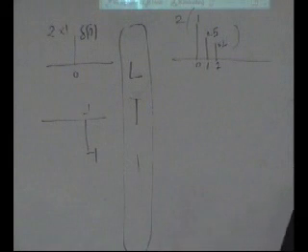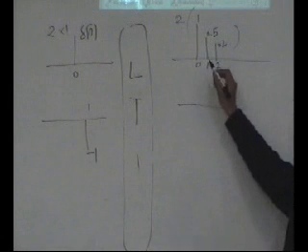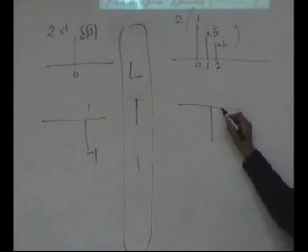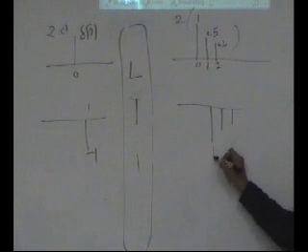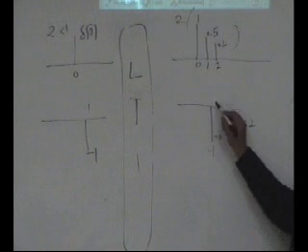If it is linear and time invariant, if you scale the input, you scale the output. If you shift the input, you shift the output. So what will you get here? You get the same signal shifted by 1 and multiplied by minus 1: minus 1, minus 0.5, minus 0.2.